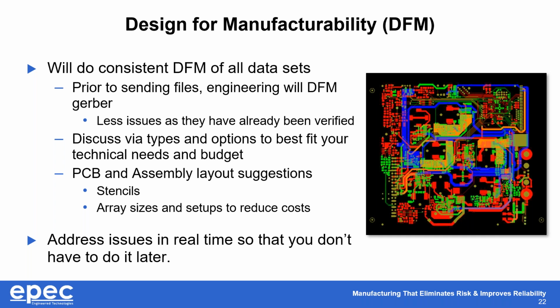We will discuss items like your vias. Are they through vias, mask-free, mask-filled? Will they be blind vias involved? Via and pad process, is it necessary because we've run out of room with our components? All of these can be done up front with your engineering team and your design team to make the best decision for you.